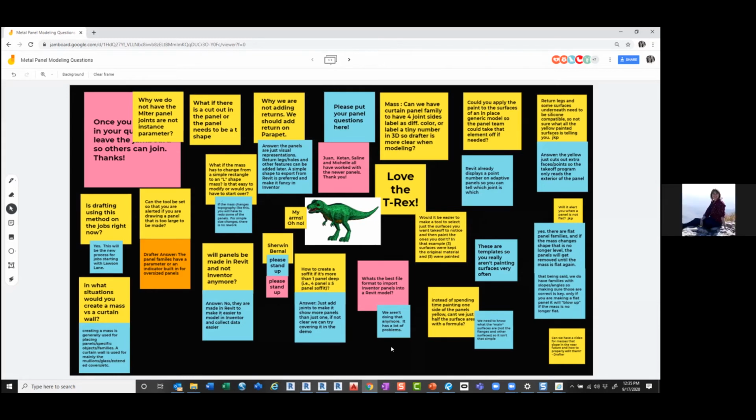If you have a tool that represents it properly for the shop drawings and for the data in Revit, and then you go to Inventor, you have to remember that if you want to bring it back into Revit, you're now completing a circle, but are you getting any benefit from it? I know a lot of people talked about that in the past with Revit, do it in Inventor and bring it back into Revit. You have to look at your threshold of change. If anything changes in those parts and you want to bring them back into Revit because they've been updated, you can get yourself into a real nightmare of change.